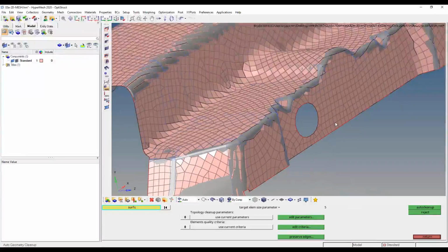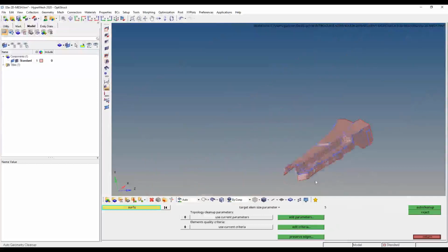But going back to the question of what I'm doing with these auto cleanup tools, right away, just make sure HyperMesh knows the average element size you're working with. And internally, it's going to build the thresholds with some percentages around that average size with some best practices. So once you specify those thresholds, the next step is to just run the auto cleanup tool. And this is going to be turning things off for you as you need it there.